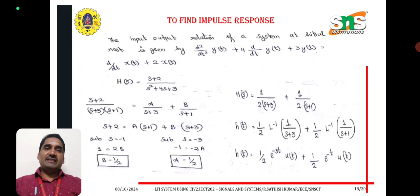S can be replaced by jω, which gives the frequency response of the system. Next one: at initial rest, d²/dt² y(t) + 4 d/dt y(t) + 3 y(t) = d/dt x(t) + 2 x(t). H(s) = (s + 2)/(s² + 4s + 3).